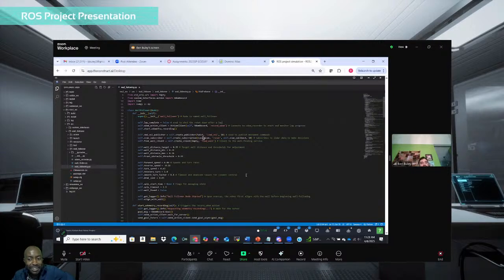And I did mess around with the fixed value. I've noticed that if I used 0.05, that would make the dead zone a larger value. But if it was too large a value, it would actually stray too far from the right wall. So with this specific threshold, it's a good balance between staying close to the right wall and not deviating too far. So this number is basically empirical, you had to acquire it through trial and error. Yes, I did. All right, that shows a lot of work there. Well done on that bit.